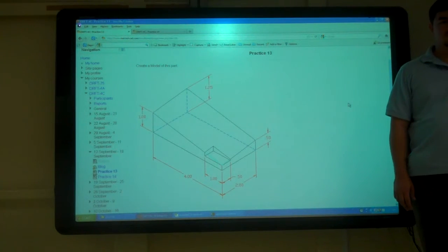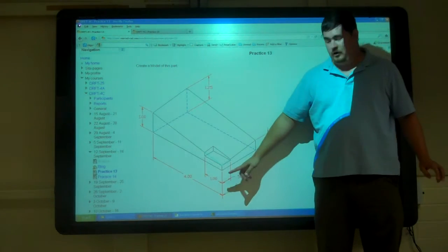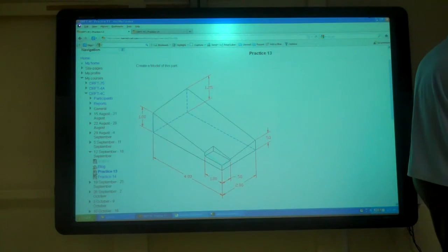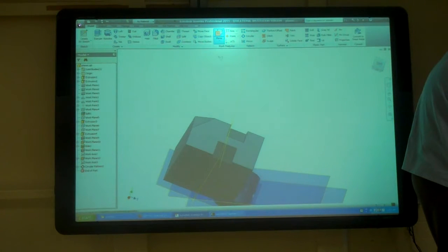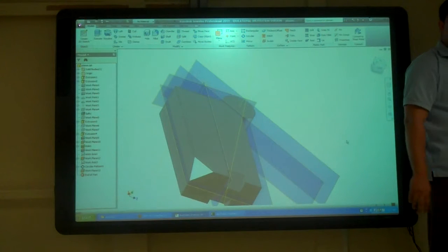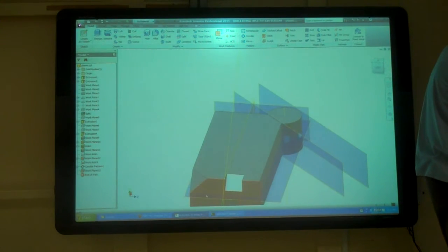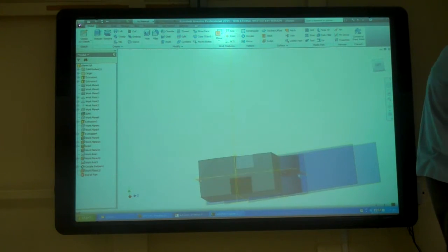After you cut this one off, wherever that corner is, you can put a plane. It's a 2-point plane. Here, you click on the plane, there, and click on that corner, and it puts it in. You're not going to know what the height is for that corner. Just click on the bottom, and that corner, it'll put it in.